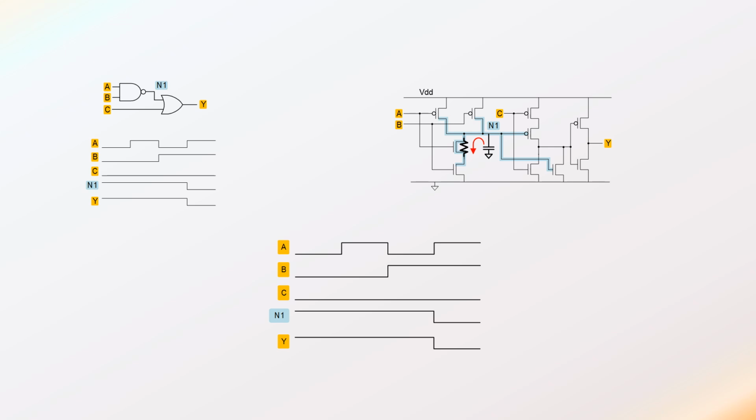I blew up the timing diagram here in the middle bottom there. Again, that's the kind of timing diagram we've been using so far, but really it should look more like this. It should show that it's not an abrupt edge that happens all at once, but there's some time involved. So I modified node 1, and that would be a voltage representation of node 1. I modified it to show a slower transition that happens over some amount of time. And that's a more realistic picture of what happens.